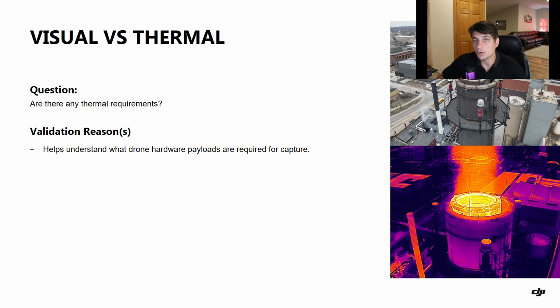But also, if you are looking to provide thermal where it may not be needed, then oftentimes you're utilizing drones that aren't going to be geotagging the imagery with RTK. If you are able to geotag the imagery with RTK, processing times are improved, the quality of meshes is going to be improved, and textures on that 3D model. So if you're going out and trying to capture something just for the sake of getting thermal, but the end user doesn't need thermal, oftentimes it can honestly hinder you. But there are definite use cases where you need to have that thermal output. And do you need to have both? Are you just looking for thermal, or do you need both visual and thermal? Huge data size comparison when you're talking about needing both, compared to just the thermal data set.